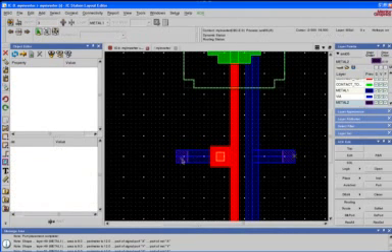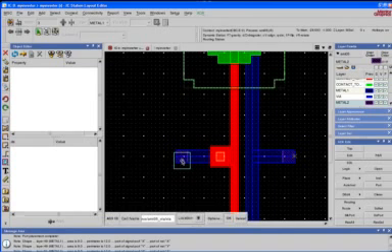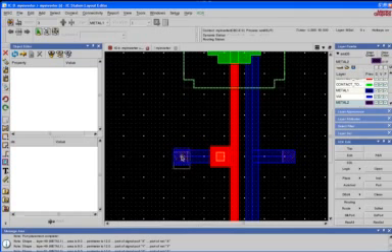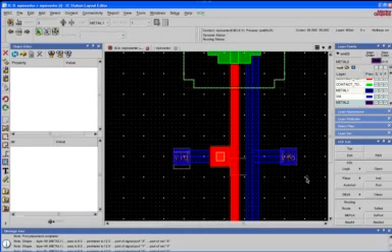Now our ports are placed on metal 2 wire and our routes are in metal 1, so we need to connect metal 2 to metal 1 using what we call a via. For that, do space, type PP, which means place port via, move it and place it directly over it. Space again, PP, which brings up port via.